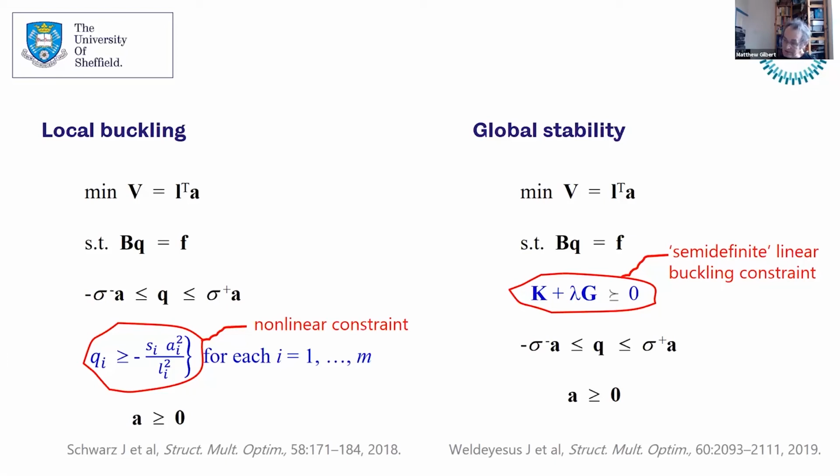For example, for tall buildings, we end up having ample opportunity to connect columns to floor plates and the like, and you end up with buckling not being too much of an issue. On the other hand, a canopy roof can be heavily influenced by, for example, global stability.